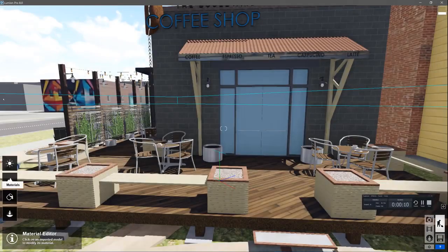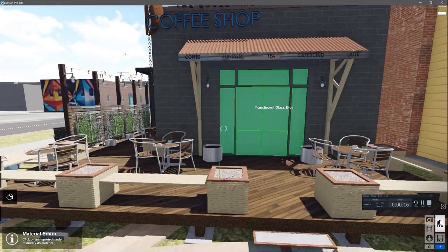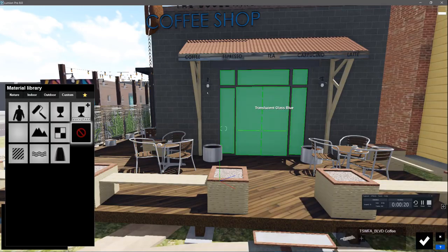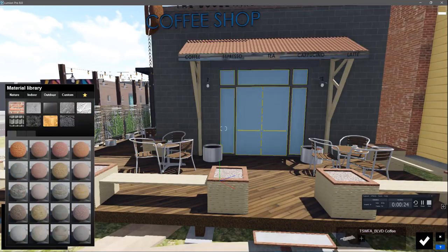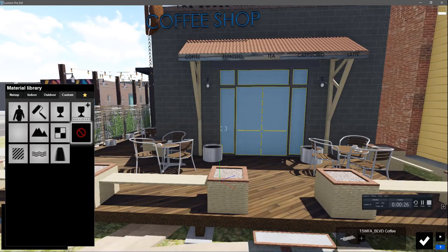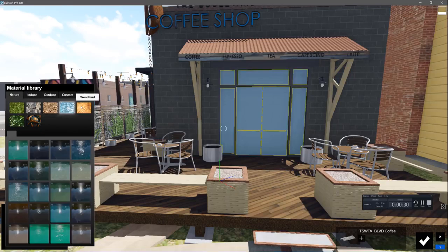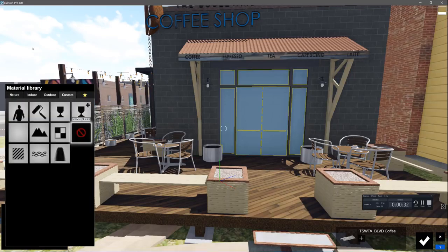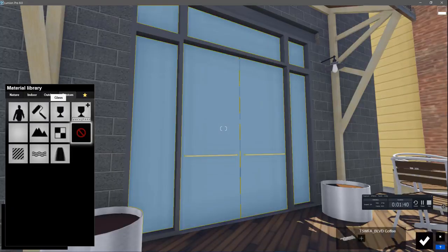Now select the Materials tab on the left. Hovering your mouse above any material highlights it. If you click on a material, you will see the Lumion material library appear. There are 4 main categories of materials: Nature, Indoor, Outdoor, and Custom. Each has several subtabs. You can either swap an imported material with a Lumion material, or you can add Lumion properties to an imported material.